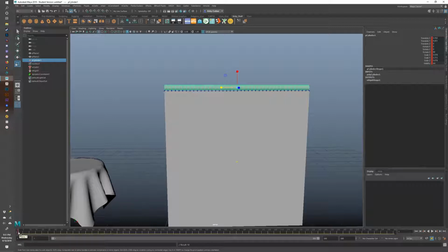And so with this keyframe, you can see over here in the properties that there are these red indicators that show you there's a keyframe for each one of these channels now. So if I advance the timeline to maybe frame 100, and then I scale in like this, you can see that it's no longer solid red, so that means I haven't locked in the keyframes yet. But if I hit S, then they're going to shift over to red, and that means I've locked in this new scale value that I've put for the cylinder.